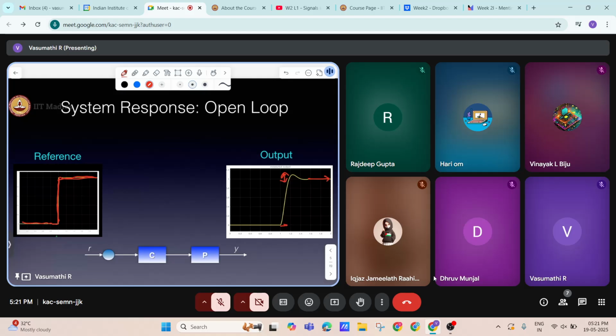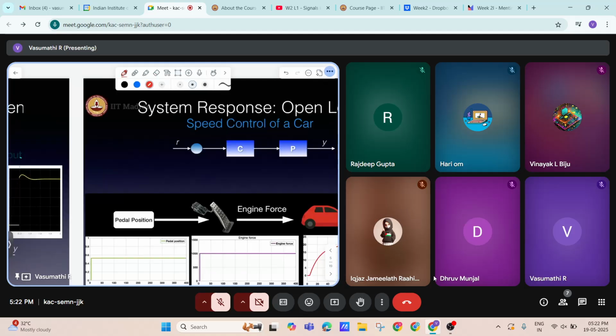But we have to design control systems such that this overshoot and this delay won't affect us too much. Within 2 seconds or within a second, based on my requirement, if the system can track the input properly, that is enough for me. But if this becomes like this, or if the delay becomes like this, then this would be a problem for me. So how much we can reduce this overshoot or the delay, that matters. That's how good we are going to design our control systems. Okay? So this is one practical example.